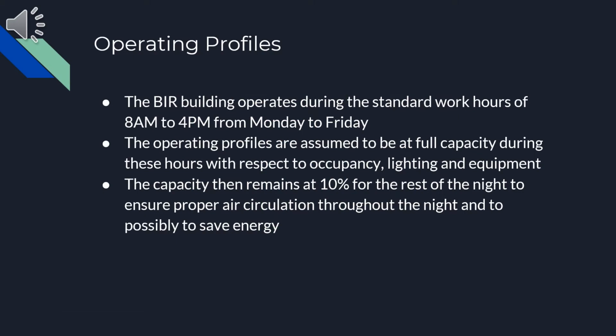My name is Carlos Mike and I will begin by discussing the operating profiles. Since this is an office building with limited daily working hours, the HVAC system will not need to be at full operating capacity 24 hours a day. The building will have different levels of usage with respect to occupancy, lighting, and equipment during standard working times, 8 a.m. to 4 p.m. Monday to Friday, a few hours before standard working time, and during the night. Operating profiles were therefore selected which were assumed to be adequate during these different periods of the day.